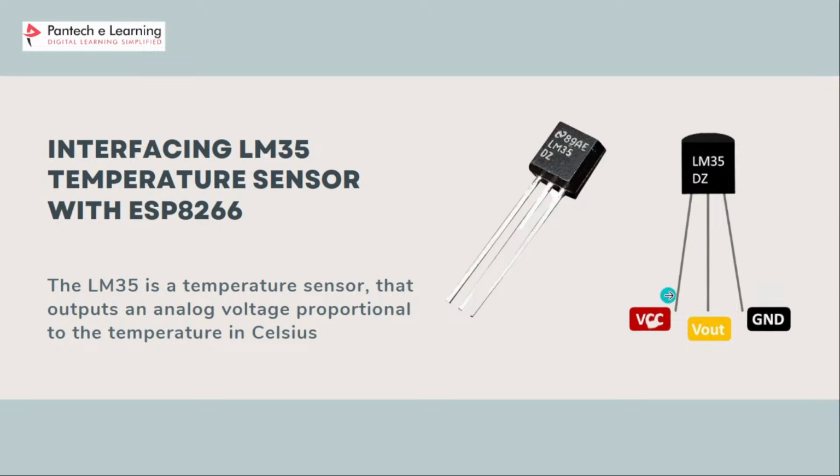If you see the pinout, the LM35 sensor has 3 pins: VCC, ground and output pin. The VCC pin is connected to the positive supply voltage, the ground pin has to be connected with the ground, and the output pin provides an analog voltage output which is proportional to the temperature. The LM35 operates over a temperature range of minus 55 degrees Celsius to plus 150 degrees Celsius.